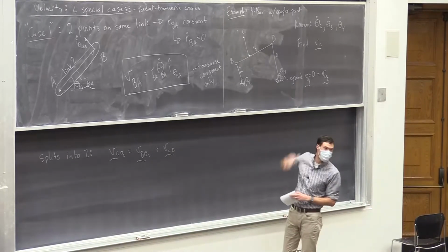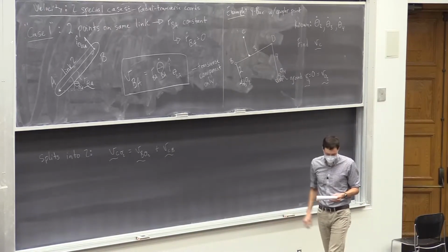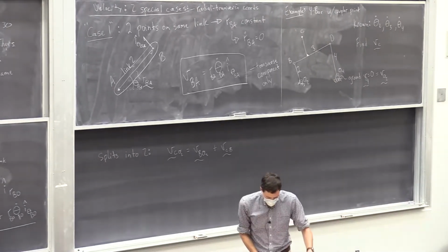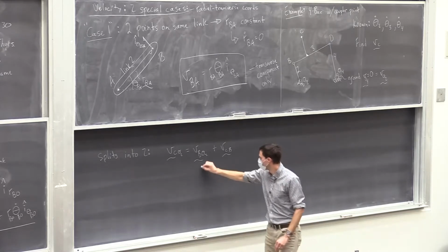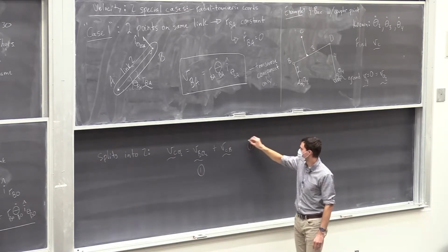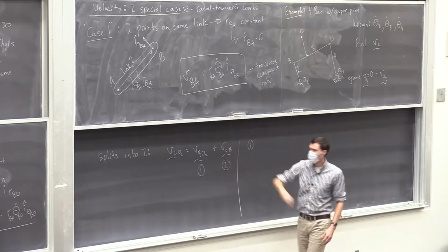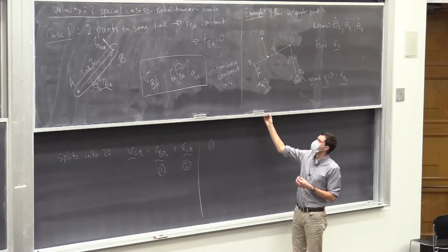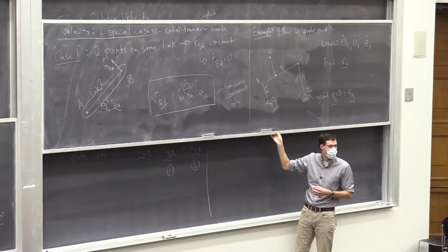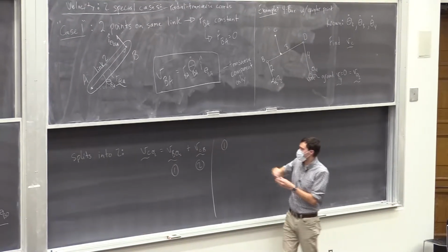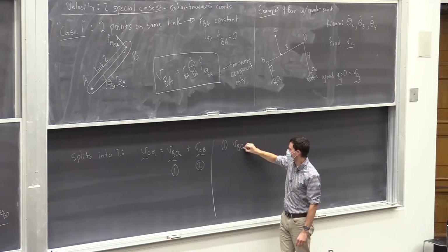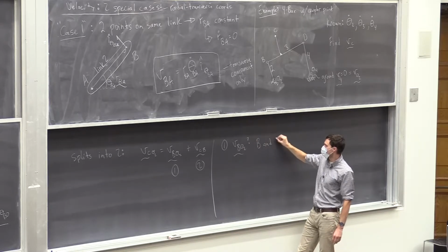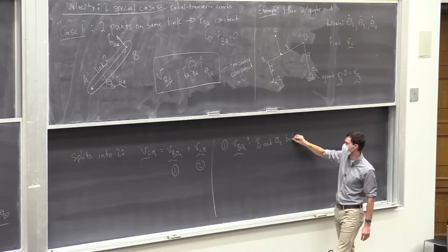Instead of B, you could have used D, and that's like going through link 4. That's an alternate solution. You can try that on your own later. So first, let's study that first piece. That's velocity of B relative to O2. And if you just look at the mechanism, you can see B and O2 are both on link 2. So that's the key. So B relative to O2, that's what we're trying to find. B and O2 are both on link 2.